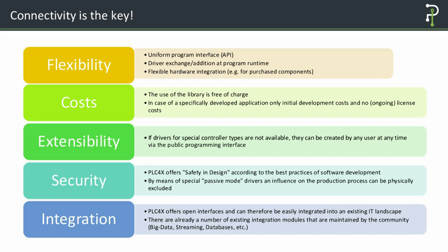Especially for PLC4X, we have a special mode of operation, I would call it, which is secure by design. Basically, it's a passive mode. So we only listen. We do not send messages on a bus. We only listen on a bus and decrypt the messages to basically understand the communication. And if you now have specific firewall rules or even specific hardware, which really only lets network flow through in one direction, then you can totally securely read PLC values from the communication.